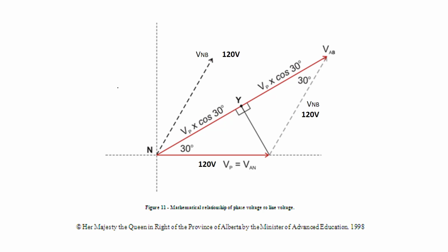So just a little thing here, where did that root 3 come from? This little diagram is in your ILM. And here are the voltages that you need to add up. You've got your VA to N here, which is 120 at 0 degrees. Here's your voltage N to B, which is 120, and we know it was at 60 degrees. It's called a tip to tail method.